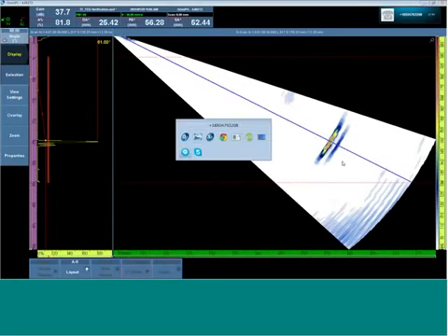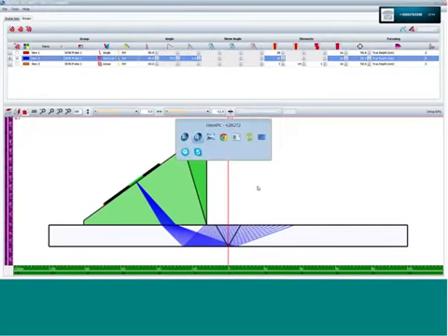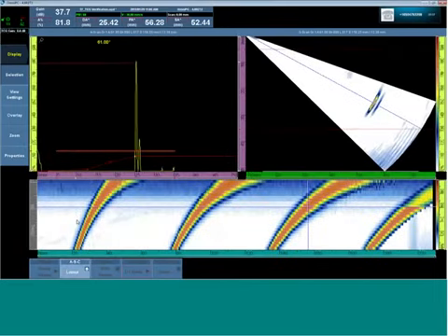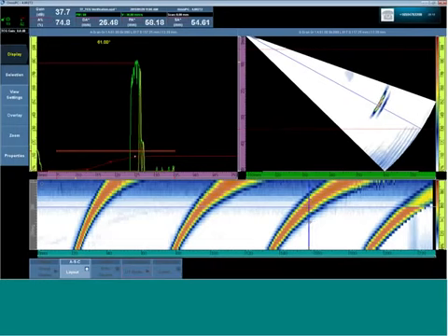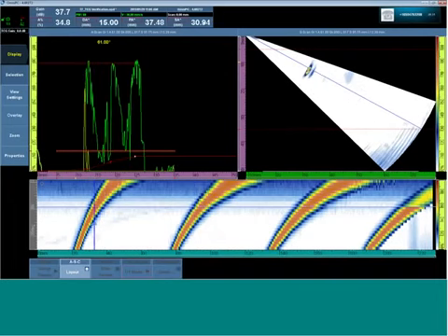And from the one-line scans that we'll be programming and learning to manipulate, like you see from a simple beam plotter here, it greatly simplifies the inspection and allows us to encode it so that with fairly simple mechanics, we can see C-scan, B-scan, D-scan type side views with a much simpler system than we used previously.